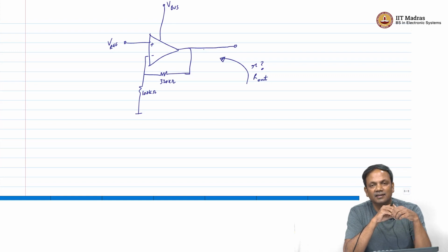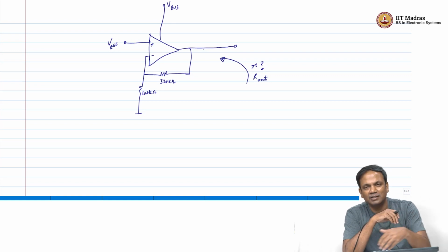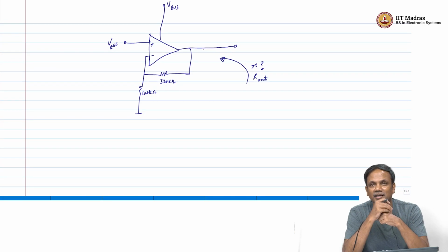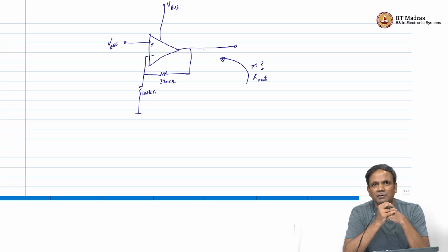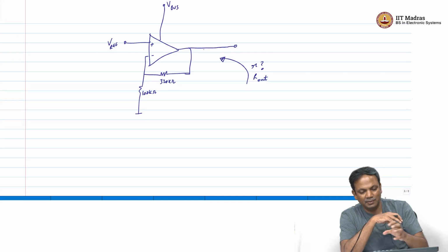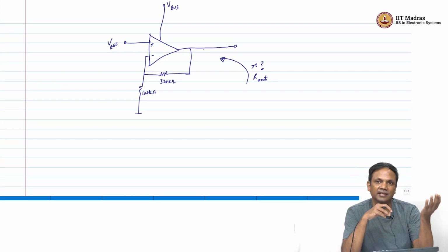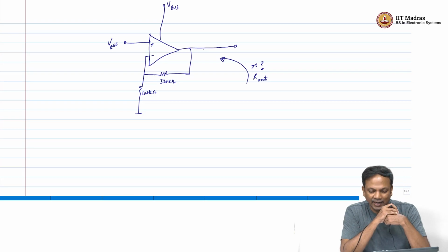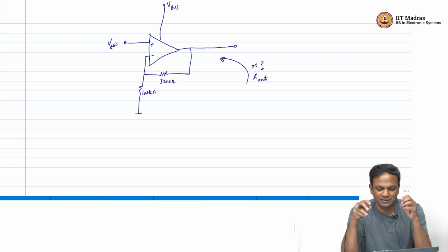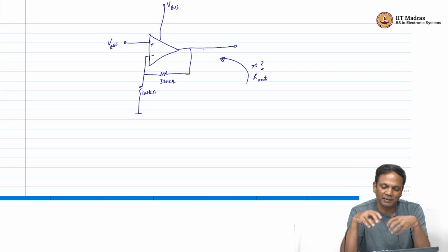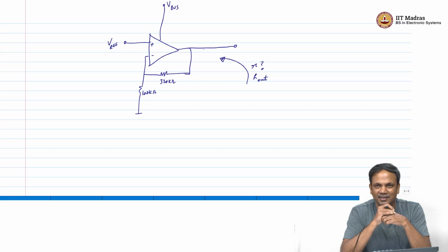I have put a large gain in that op amp, and that gain multiplied by the attenuation factor is my loop gain, and R_O divided by 1 plus loop gain is my output resistance, and that will be very low because my loop gain is high. I am building a voltage controlled voltage source. Voltage controlled voltage sources will have low output impedance because they have to supply a lot of current, so everything about these statements is correct: the loop gain is large, so output impedance is low, it is a voltage controlled voltage source, so by design output impedance will be low.